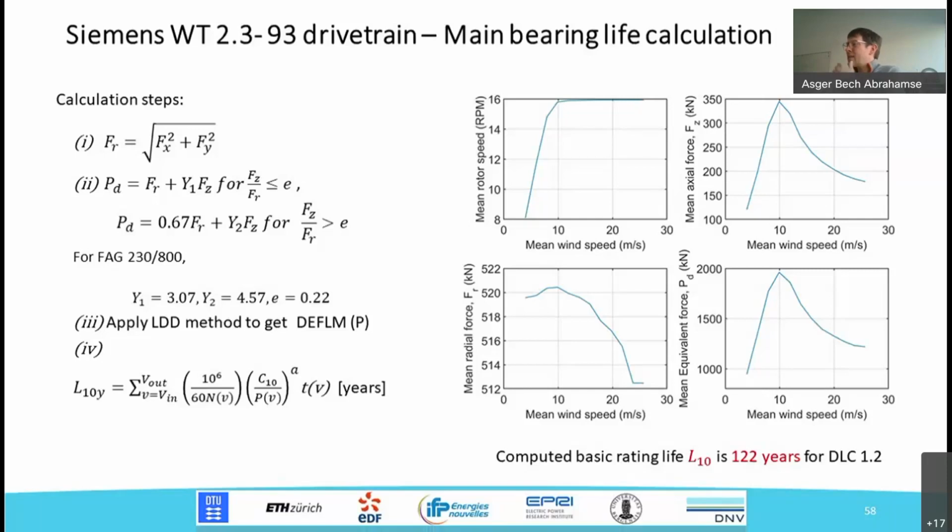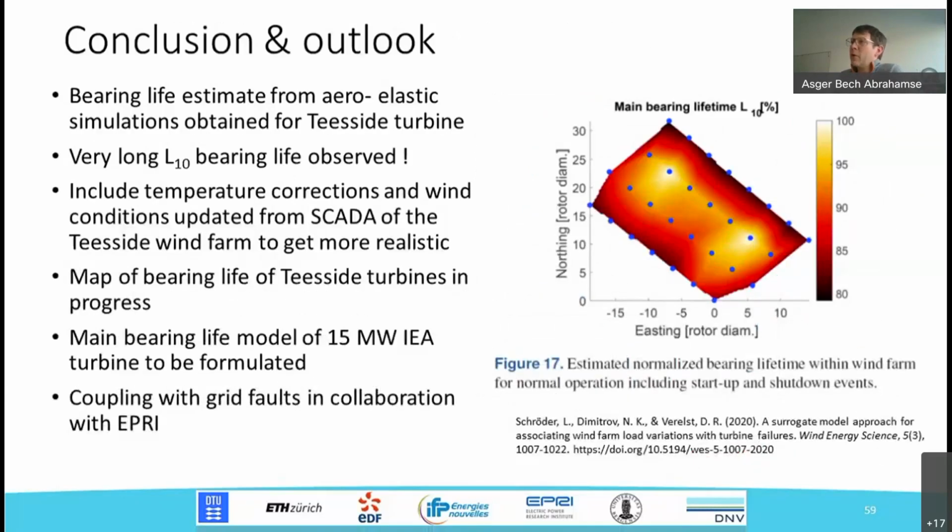And you might say, that's long, right? Because many of you probably know that according to the IEC standards, we are designing offshore turbines with a design life of 25 years. But one of the things is that this L10 bearing life is very crude. And if you go into bearing manufacturer specifications, they prescribe that you need to look into what the temperatures of those bearings are under operation, because that reflects the viscosity of the lubricants, and also the cleanliness of your lubricants.